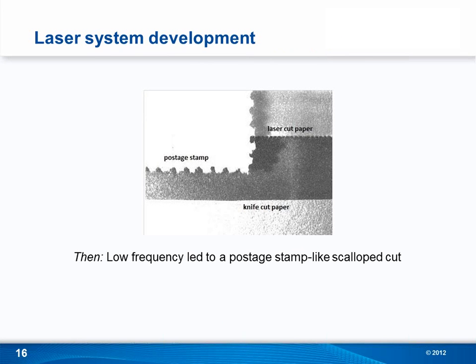To talk a little bit more about the laser, to get an idea of the pulsing problem, the top left corner of this image shows the edge of a postage stamp, and I use this to clarify what the laser does. If you move the metal too fast under the laser beam, the pulses become separated from each other and the metal wouldn't be dropping out of the intended aperture. So you have to either increase the pulse rate of the laser or decrease the speed of movement.